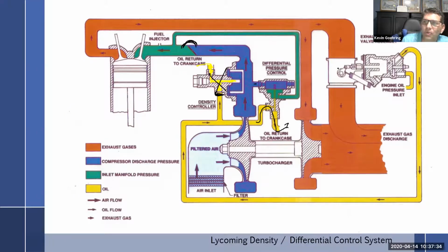opens or closes to where it should be to maintain the proper differential. And then this closes back up again. And, you know, it opens up a little bit and drains a little oil, closes a little bit, holds it in. It's always moving a little bit, doing what it needs to do to keep this thing at its point. Is that a diaphragm in there? Yes, it is. A diaphragm with a spring.